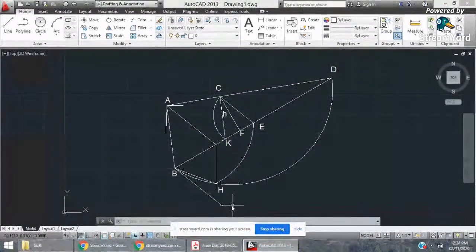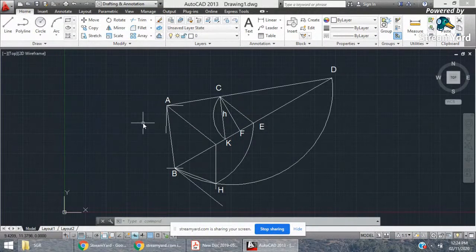Okay, so here what you have to do is first take one vertical line. Take the batter angle theta equals 0 degree or 5 degree, 10 degree, whatever is given. Draw the AB line. After drawing the AB line, draw a phi line. Phi equals 25 degree was given to us. So we have drawn the phi angle. Then from here, the inclination angle is given to you. Surcharge angle beta, which is given to you as 10 degree. So we have drawn it and we have got the intersection point.